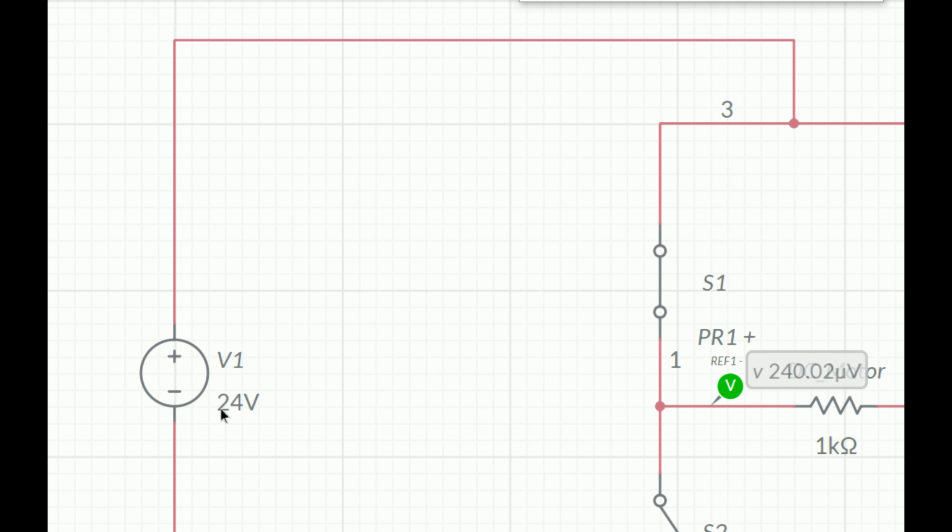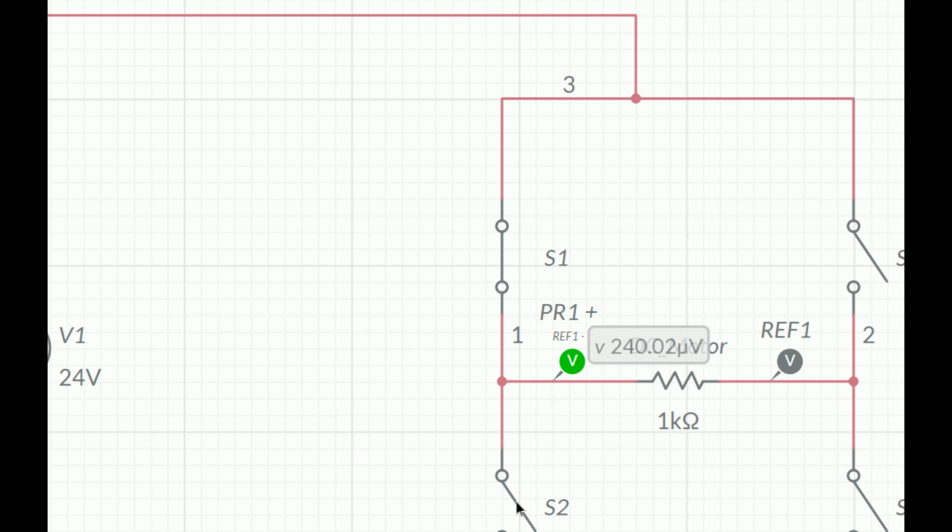our supply is 24 volt. Now once we close this switch, positive coming from here goes on the left side, through this switch to this terminal of the motor. Now this terminal of the motor is getting the power, but at this terminal we need a negative. We don't get negative here. From the bottom side, this is the negative side and both the switches are open. Now to get negative here, we need to close this switch. Now see, 24 volt.